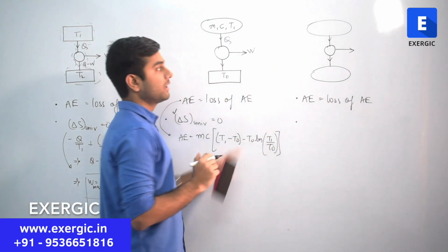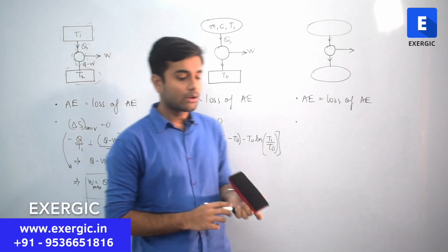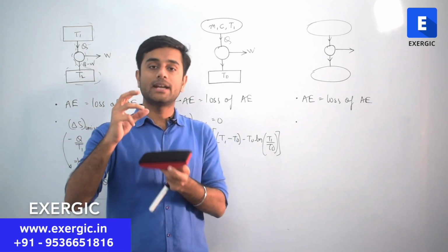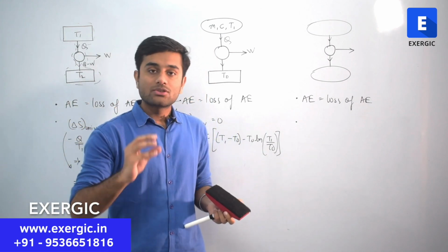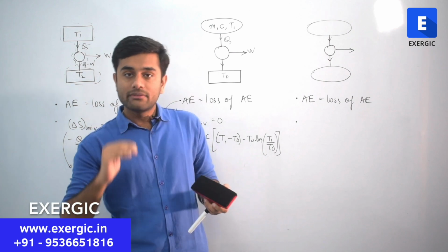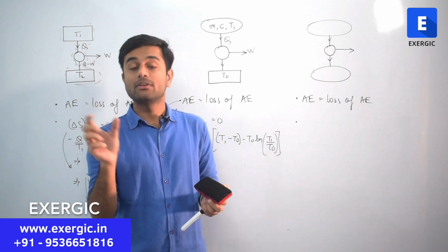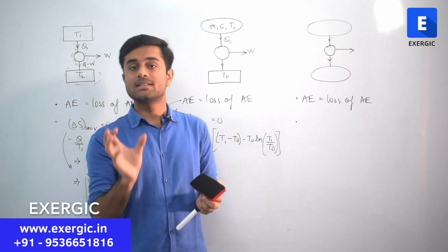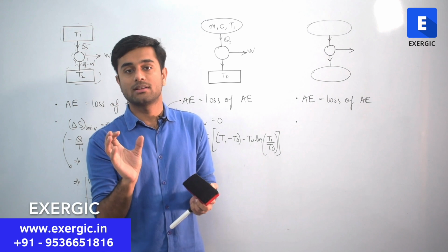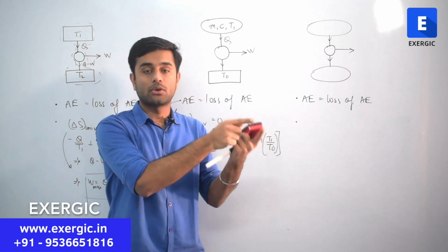Similarly, in this case, you recall that I told you that whenever we are going to transfer heat between two finite masses, the range of work will vary from the average temperature to the geometric temperature, from T1 plus T2 divided by 2, which is the mean arithmetic temperature, to the geometric temperature, root T1 T2.